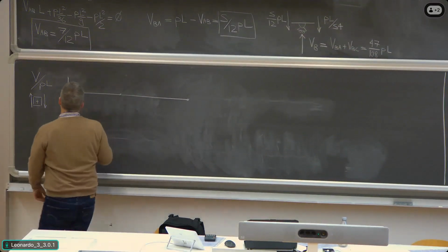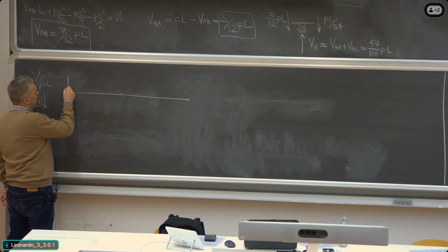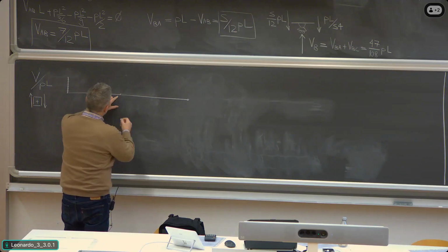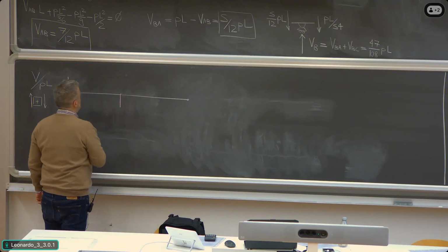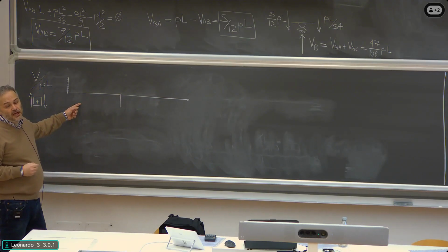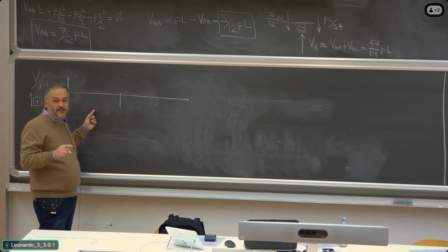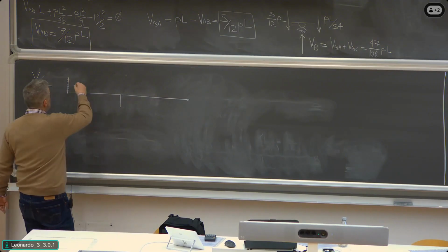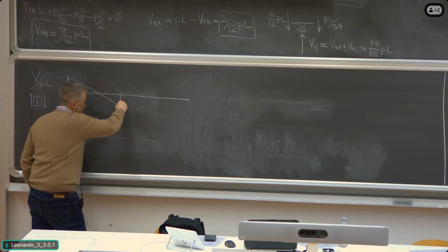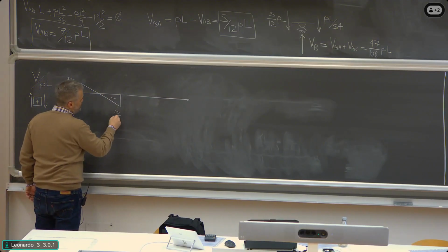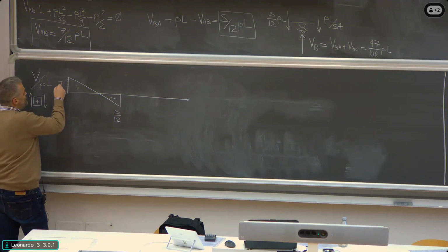So here you have to be careful. So divide this in 7. 1, 2, 3, 4, 5, 6, and 7, which means this is 5. Plot it in the scale. And then in the middle, how is the shear force going to be? With distributed load, the shear force is linear. From a positive value to a negative value, which means it's a straight line going like this. This is positive, this is negative. Here you write 5 over 12, and here 7 over 12.